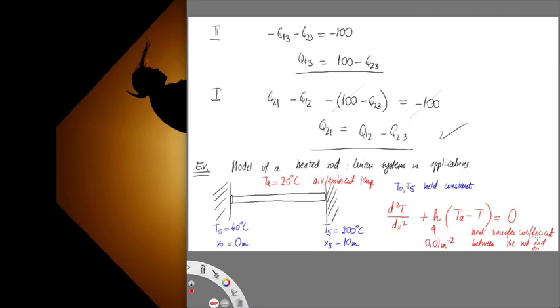The moment we're looking for it numerically, we are unable to solve T of x for every possible x because there are infinitely many between 0 and 10 meters. But we will discretize our line into a one-dimensional problem. We're going to simplify this as temperature at every point in one dimension. And for simplicity here, I'm going to discretize it so I have four points. 1, 2, 3, 4.